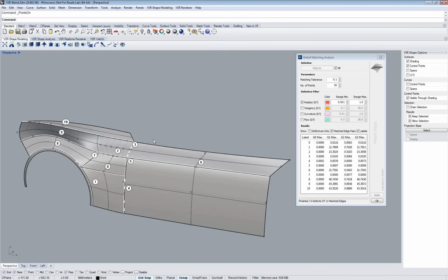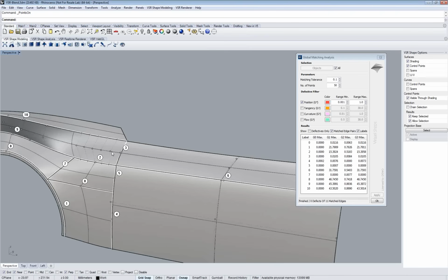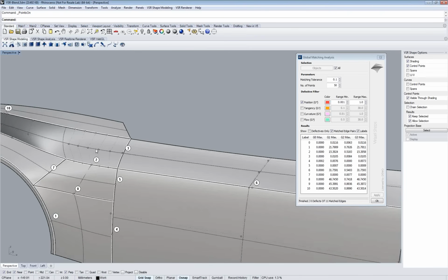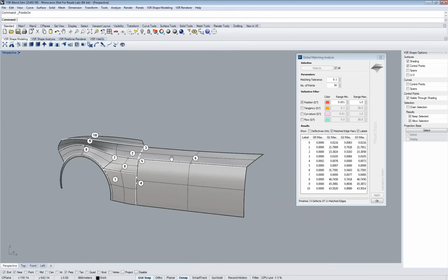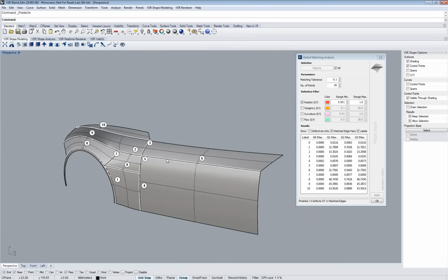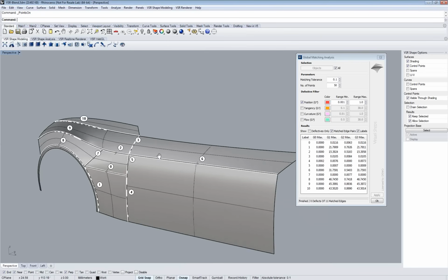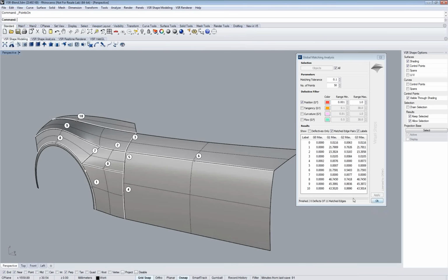So if you've got the choice which surface to match, take the one with a higher control point number, where the control points stick together more closely, because then matching them moves these control points not that much, and you are not affecting the shape as much as you would if you did it the other way around. So this is also a general thing you should remember when trying to make good surfaces. You have a global shape, and you're trying to touch it as little as possible.